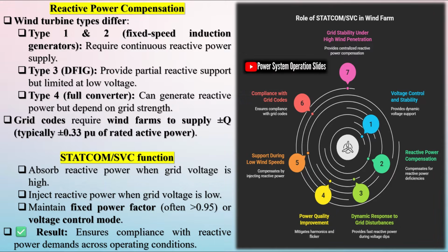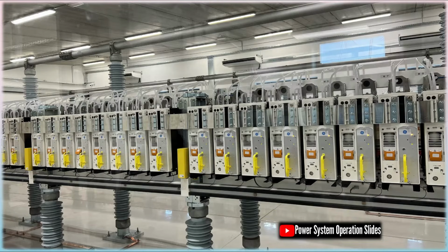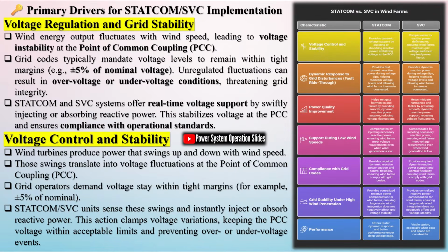Functionally, Statcoms deliver both inductive and capacitive reactive power with high accuracy and speed. This dynamic capability allows them to outperform traditional solutions like capacitor banks, shunt reactors, and synchronous condensers, which often suffer from slower response times and mechanical limitations. Modern Statcoms also integrate multiple control functions, enabling them to address power quality issues, provide ancillary grid services, and support the integration of clean energy sources, all within a single compact device.